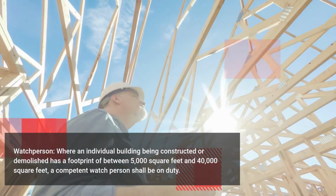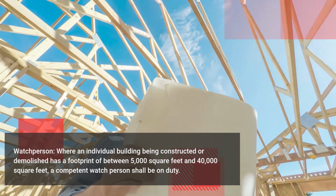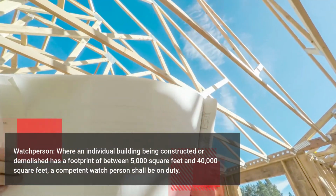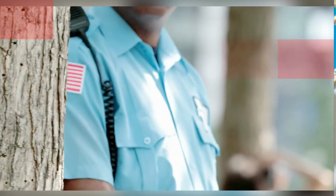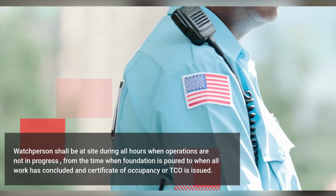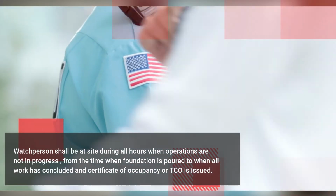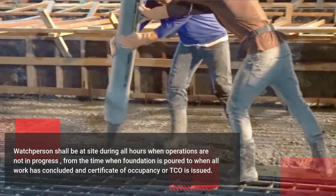Watchperson. Where an individual building being constructed or demolished has a footprint of between 5,000 square feet and 40,000 square feet, a competent watchperson shall be on duty. The watchperson shall be at the site during all hours when operations are not in progress, from the time when the foundation is poured to when all work has concluded and a certificate of occupancy or TCO is issued.